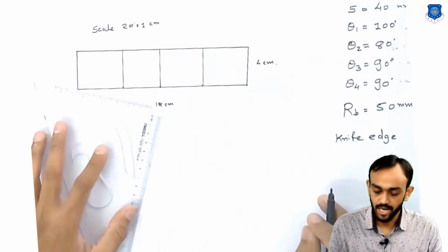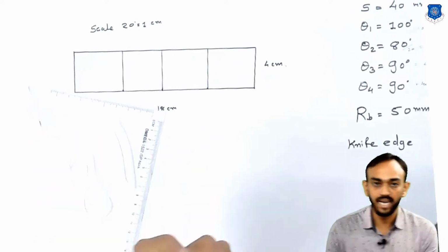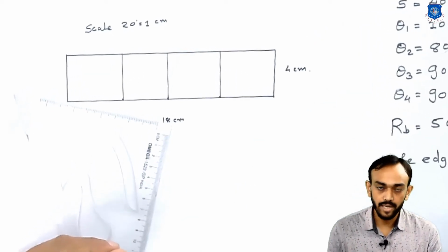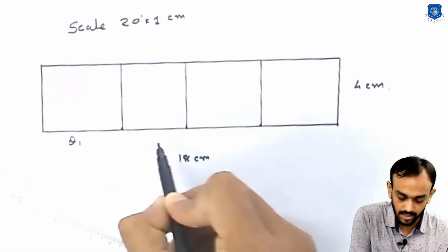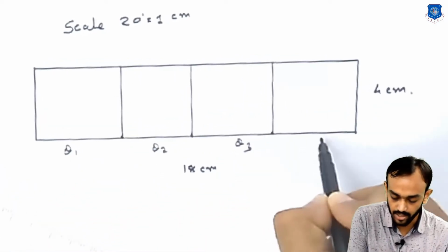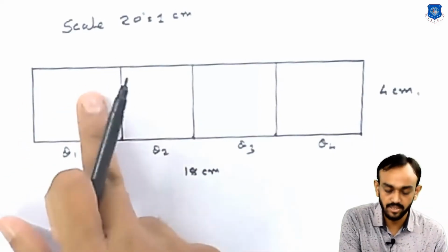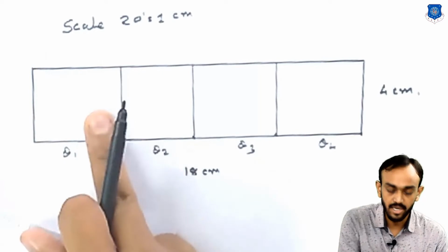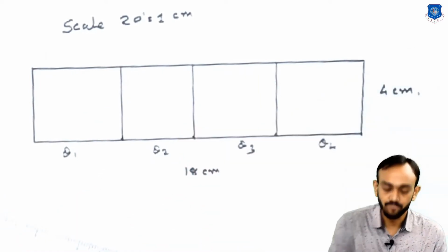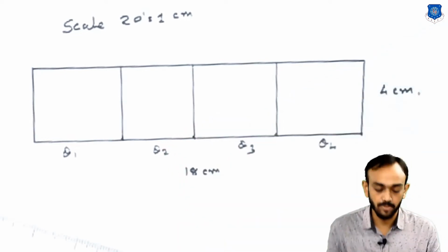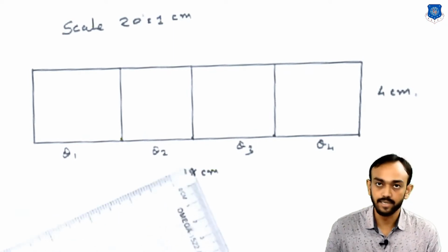Now, as you know, in all displacement diagrams we divide the rise and return into 6 parts. The rise is 5 centimeters here, theta 1 is 5 centimeters; this is theta 1, theta 2, theta 3 and theta 4. So theta 1, this 5 centimeter division we have drawn, we have to divide into 6 parts, and theta 3, which is 4.5, we also divide into 6 parts. So how can you divide any rise and return?